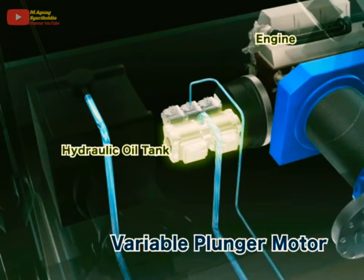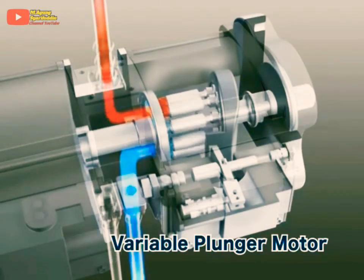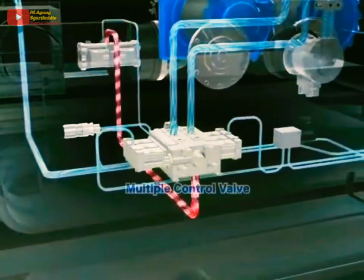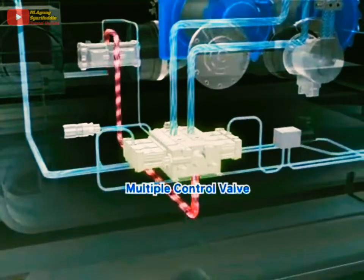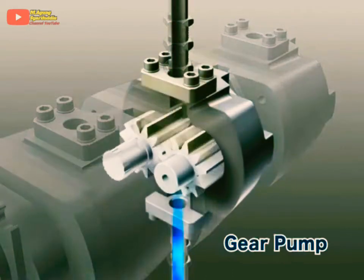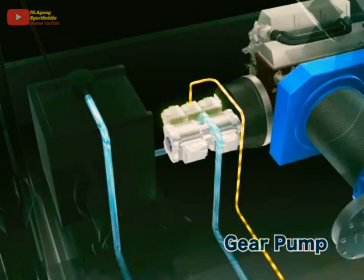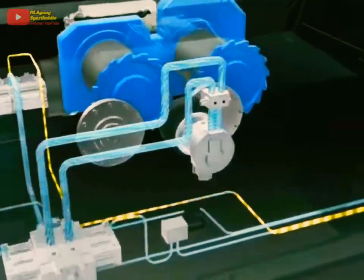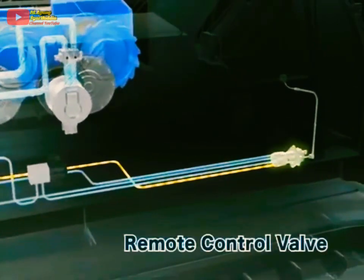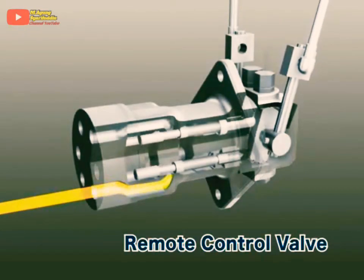First, the variable pump is driven by an engine, sucking hydraulic oil from the tank. The oil is then sent to the multiple control valve. At the same time, the gear pump sucks and delivers hydraulic oil to the remote control valve. The remote control valve is connected to the levers in the operating room, where the operator selects which outlet port to send the oil.